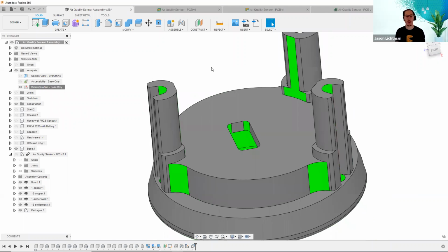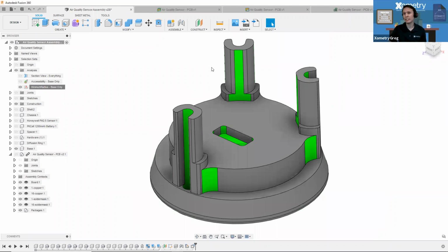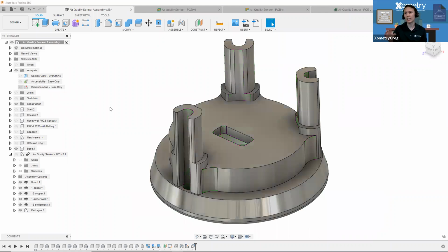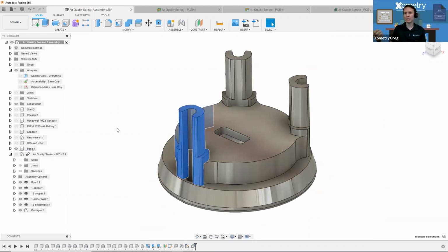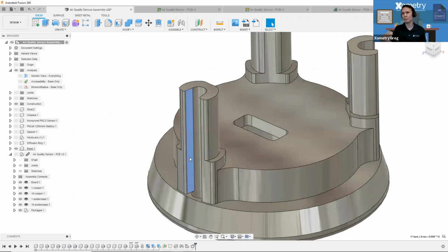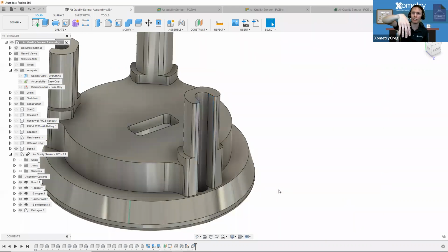What else do I need to change before I go and CNC machine this? So again, the other cost driver that I see here is you actually have on those three bosses, they're not quite bosses, they're kind of open on one side. And when I'm milling that, it's not just a drill, right? So now I'm actually pocketing. I need to take a really long, thin aspect ratio end mill and cut in that kind of U-shaped pocket there. And that's going to add time to making this part.